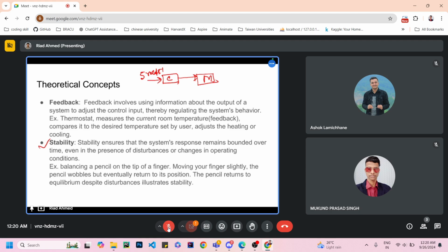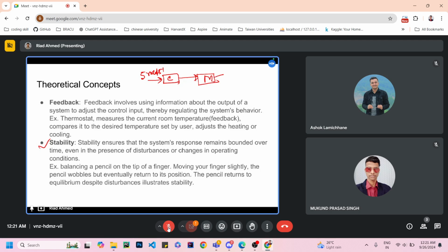That is the goal of the controller. Now, the controller will not jump to 5 radian per second from the beginning. Firstly it will try to increase the voltage, and it will see what the actual velocity of the motor is at that time. Maybe at first the motor will have 2 radian per second.